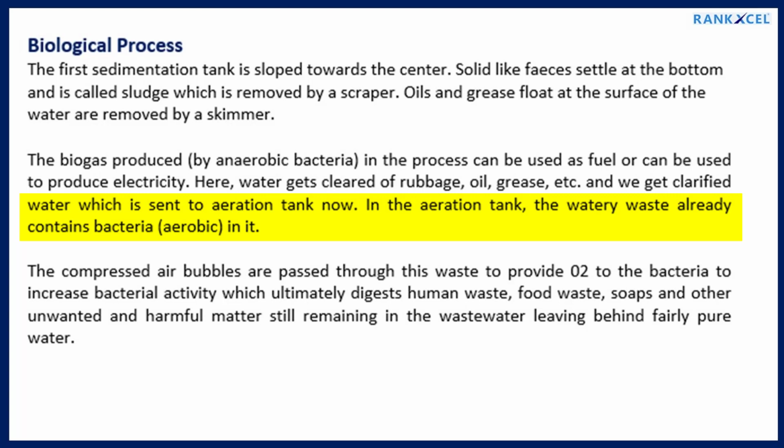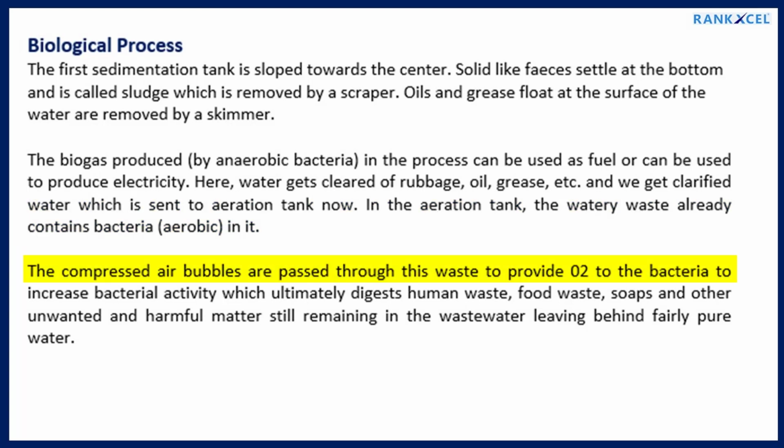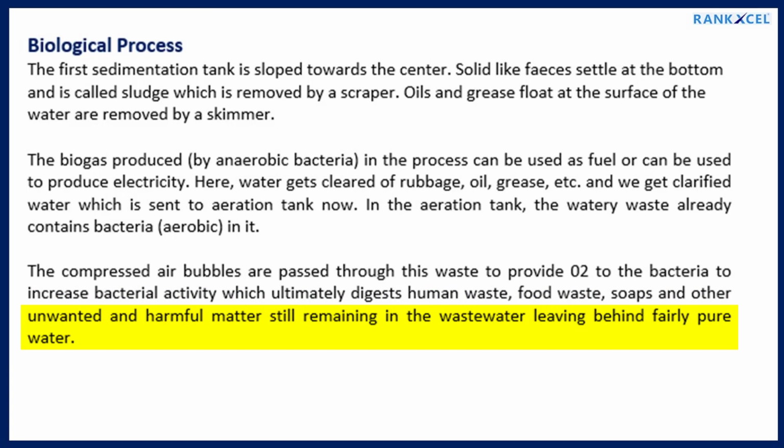In the aeration tank, the watery waste already contains aerobic bacteria. Compressed air bubbles are passed through this waste to provide O2 to the bacteria to increase bacterial activity, which ultimately digests human waste, food waste, soaps and other unwanted and harmful matter still remaining in the wastewater, leaving behind fairly pure water.